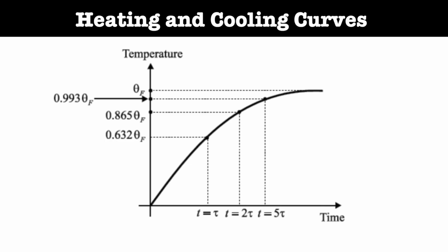If we consider a homogeneous machine developing heat internally at a uniform rate, and it dissipates heat to the surroundings proportional to the temperature rise, it can be proved that the temperature rise of a body obeys the exponential law given by the expression.